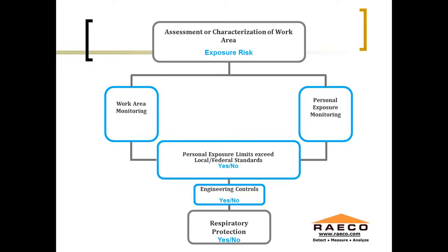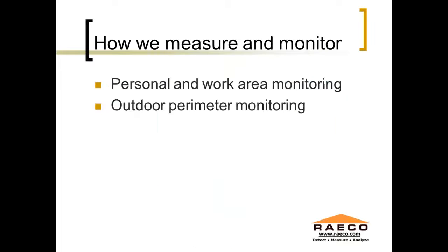The nice thing about real-time based measurements is that if you take a sample with a gravimetric for 8 hours and you don't really see anything, maybe you see a little bit of an increase from one year to the next, you don't know what time of day that's happening. The only way to do that is either to do a real-time based measurement where you can get a trend over 8 hours, or basically observe that entire workplace for 8 hours yourself. And since we're all busy, that tends not to be something people want to do, and so it makes a natural fit for real-time technologies.